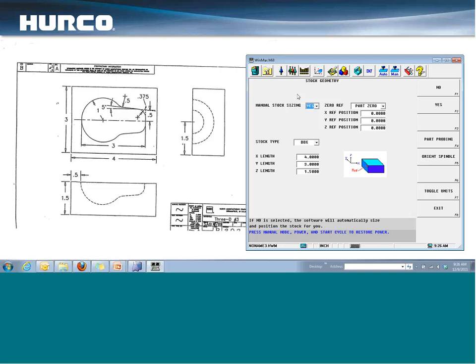What it's meant to do is, if you set all 3 of those things up, your graphic screen should look exactly like the part that you intend to take out of the machine. I like to put it in in case I forget minus signs, or maybe I make something too large. The example I like to fall back to is, if all I'm doing is cutting a circle in the center of a piece of material, if I give it the diameter rather than the radius, it's going to cut that circle twice as big as it needs to be.